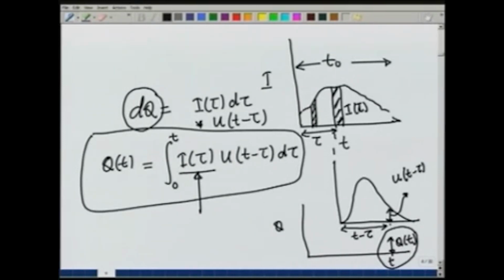Now, we should look at how to derive the IUH. As we have already discussed, it is a very small duration rain, total depth of 1 centimeter. So, one way of deriving the IUH is using the S curve.